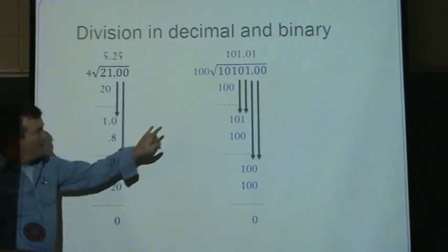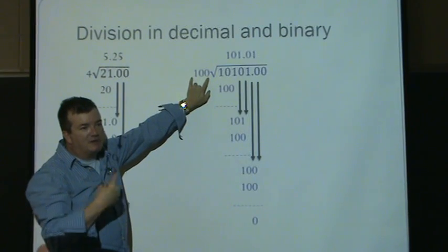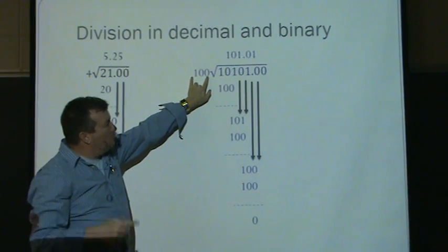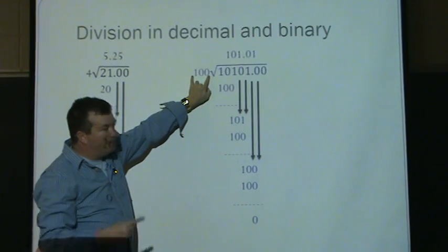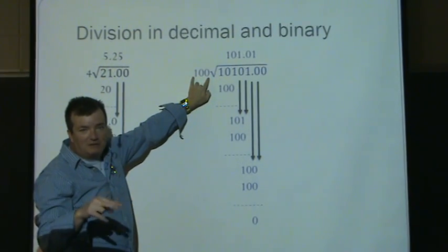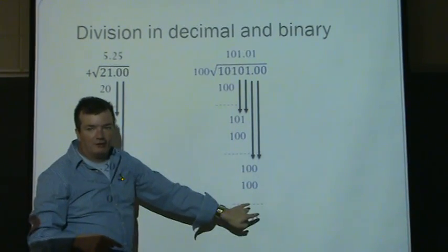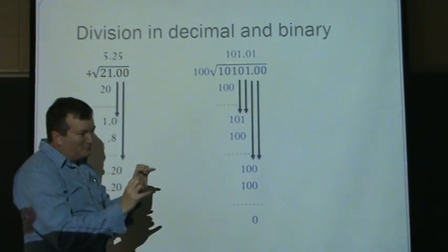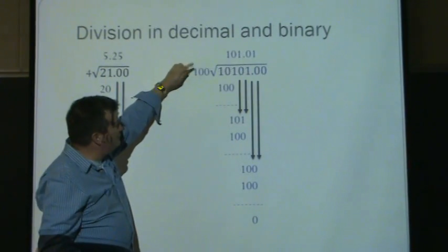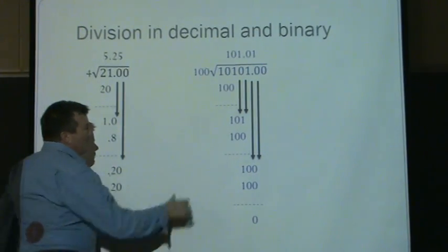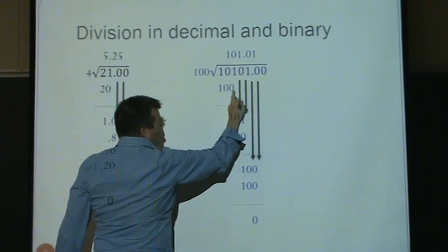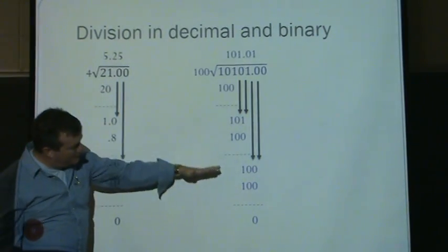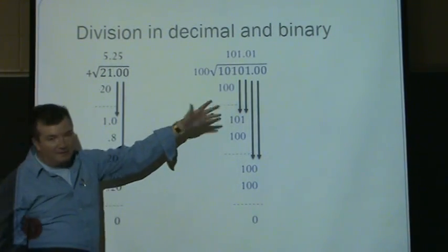But we know that if you take a positive number and you write it in 2's complement form, now you have the negative of it. If you add the negative, that's the same as subtracting. So one thing we want to do before we start a division, we want to take the thing we're dividing by and immediately convert it into a 2's complement version of itself, because we're going to keep subtracting it over and over. And we don't know how to subtract, but we know how to add a negative number. So one of the first things we'll do before we do a divide is convert this into a 2's complement, which is just flip over every bit and then increment it by 1. Then we just keep adding. So every time I say subtract 101 minus 100, I'm actually saying add the 2's complement of this. And then we could just do this computation until we hit a 0, or run out of bits, and then we're done.